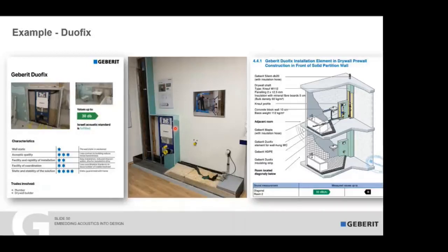So also here with Knauf W112, and already here you see the downpipe is all DB20 pipe, so acoustic pipe, but the branch pipe here, as we have a same floor installation, we can still do with HDP pipe, no problem. There will be no interference to the neighbor which is below. You see the pipe is all above, and like this we can guarantee the 30 dBA in the neighbor's flat,